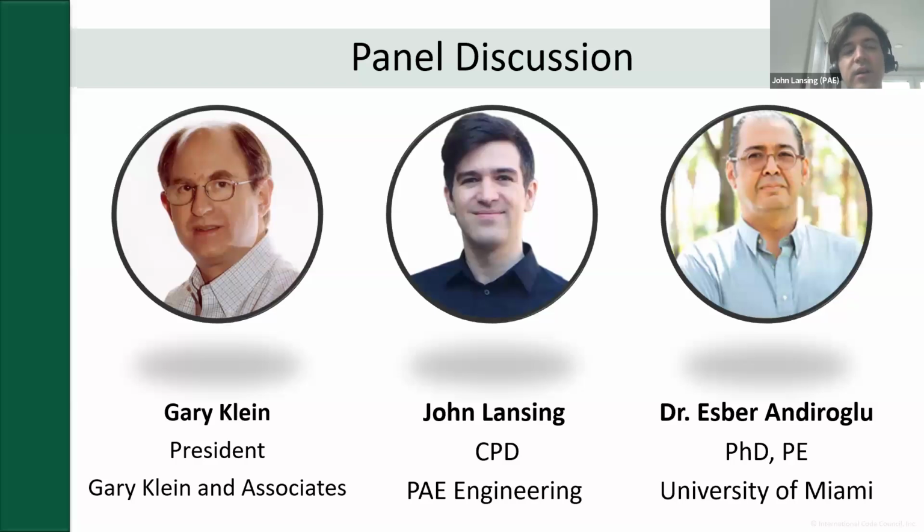Yeah, I second those thoughts. So, closer to the fixture, we'll often see a lot of discussion around 3-inch or 4-inch in terms of the connection to the water closet, right? And there was some research done at the PERC, the Plumbing Efficiency Research Coalition, several years ago now, comparing the performance criteria of the 3-inch and the 4-inch. And what the research found was that the gradient was actually a bigger factor than the diameter difference.